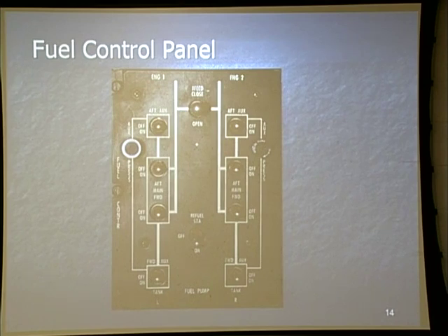So if the light's on with fuel remaining in the aux tanks, then you've got a pump problem. If the lights are on and there's no fuel remaining in the aux tanks, then it did what it's supposed to.